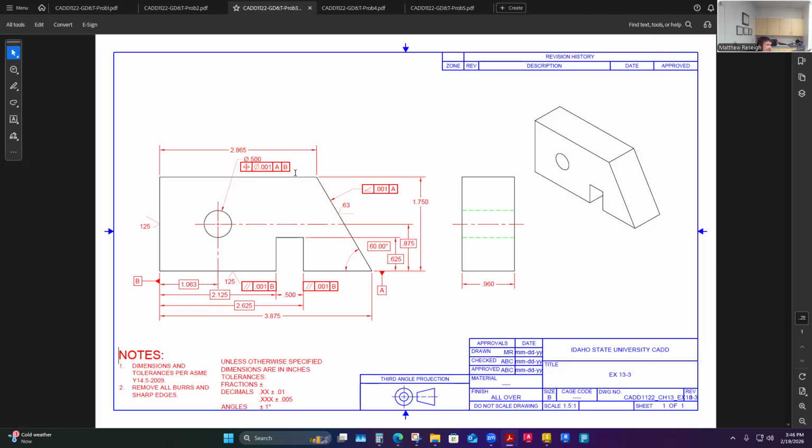So I'm not going to gain any bonus tolerance. No matter what, it's a half-inch hole with plus or minus 5 thousandths, which is essentially how the tolerance is applied. Regardless, I have to hit that. That's one criterion I have to hit. So it has to be a half inch plus or minus 5 thousandths, and that's an acceptable size. Anything outside of that would be rejected.